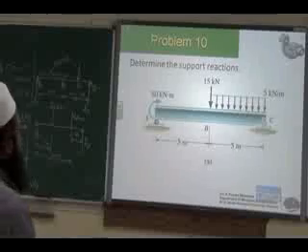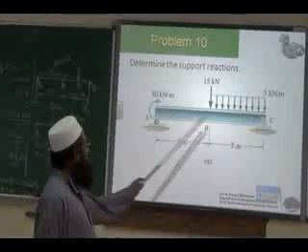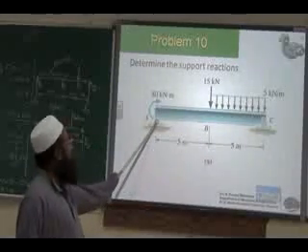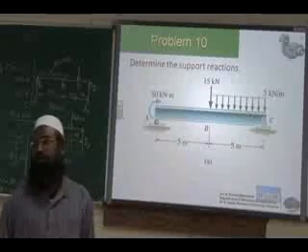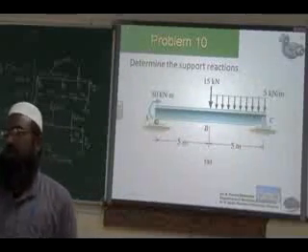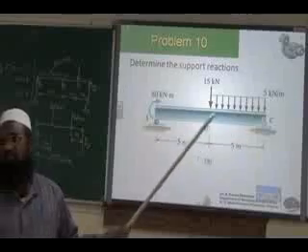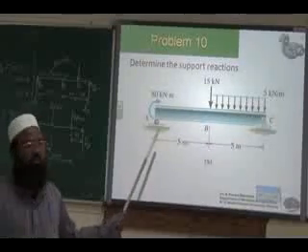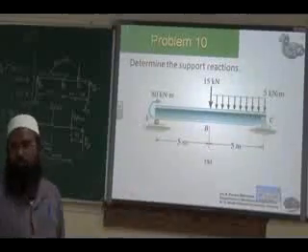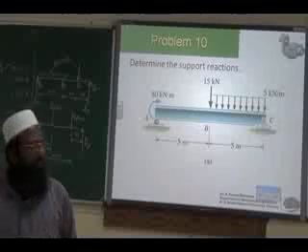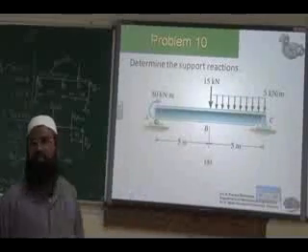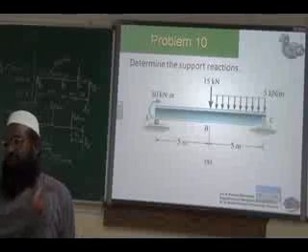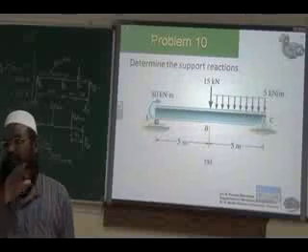Okay. So here the support is different. You have a simply supported point A and hinged supported point C. So point C will have two reactions. Point A will have only one reaction. A moment is applied at point A. Applied moment is there. It is not a reactive moment. It is an active moment. Action.